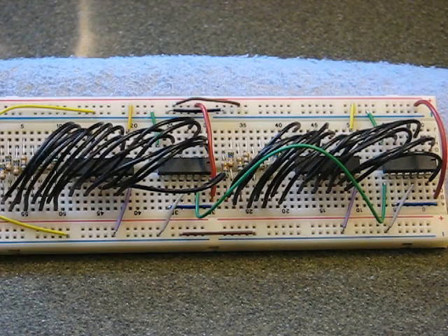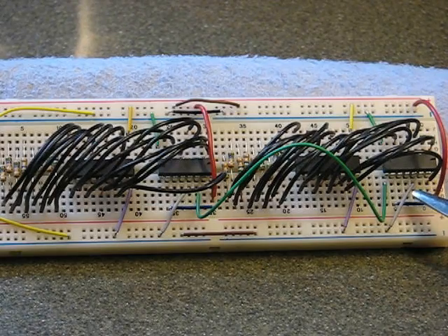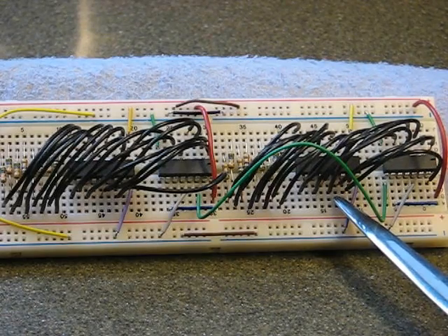Okay, so what I want to do here is show you a close-up of the electronic components that interface between the Arduino and the cabinets. Each cabinet has one of these breadboards. I hate soldering. It has a breadboard with the stuff it needs and a bunch of wires from here to the cabinet. So what happens is the Arduino has 3 wires that come out here and is connected to this first chip, which is called a shift register. It splits my byte into 8 bits. The 8 bits come across these wires here to this chip, which is a transistor array.